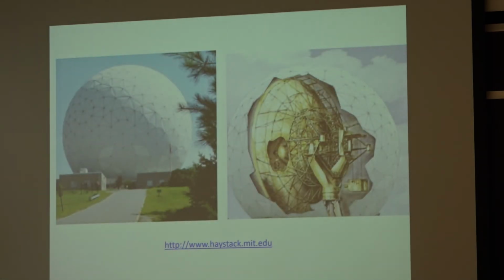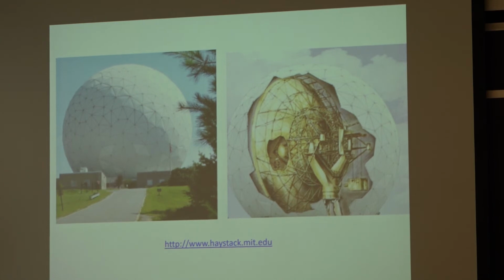So, we do use aluminum a lot. This is a specific application of this radio telescope that has a very specific dish structure to look at what the other side of the world does and other things. What you see, the outside enclosure is white. That's kind of to protect against the environment. And then the inside enclosure has the system that can tilt in two directions. This is about 200 feet or 80 meters in diameter. And it needs to stay the same shape within some tolerances when you tilt it.